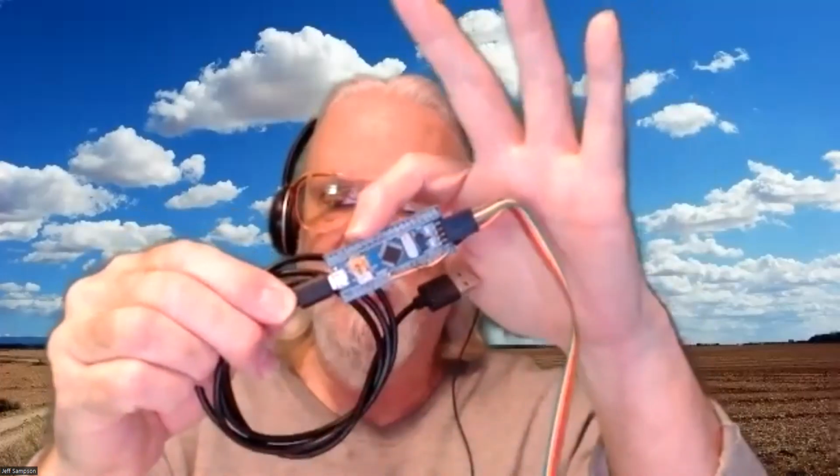Basically, the Black Pill, which has the Cortex M4 processor, has the built-in bootloader for the DFU mode, and it's got the built-in bootloader for serial mode. So you can use either of those. And then back on the Blue Pill, it's got the jumper on there. It's got actual jumper pins. You have to move it and then hit reset, and that puts it into serial bootload mode. So again, you've got a couple pins out here, hook it up to an FTDI adapter.